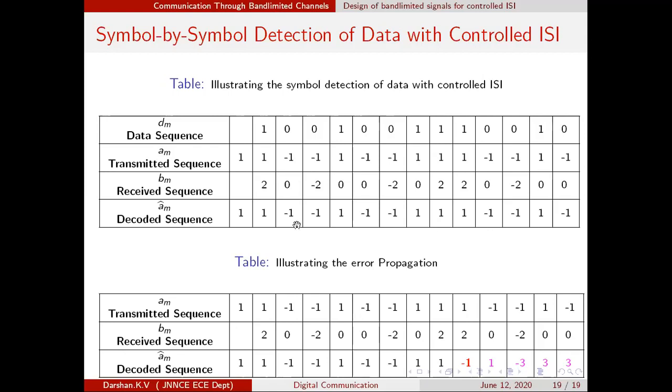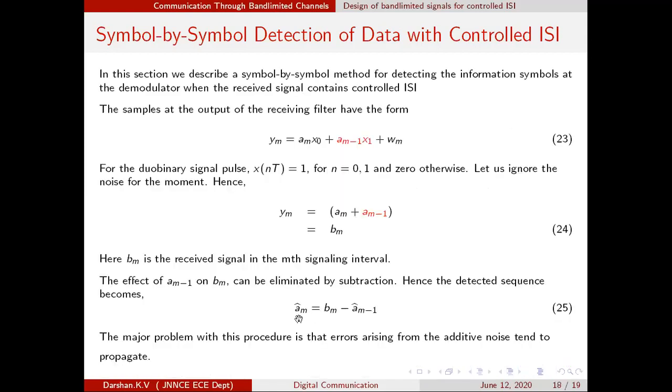So therefore, what they did was, here they have written this is the received signal till here. Now from the received signal we need to detect which symbol has been transmitted. So I have written the BM. What was BM having? Current symbol and the effect of the previous symbol. How was the effect defined? Addition. So now what will I do? I will do subtraction. Therefore I will introduce this minus sign. What do I need to subtract? The previous transmitted symbol I need to subtract.